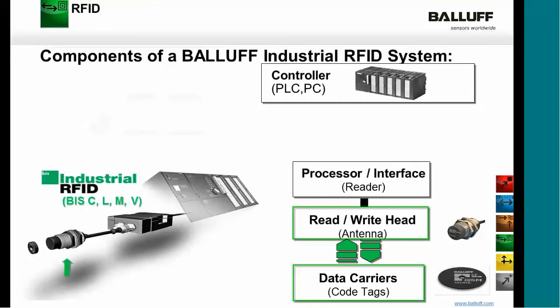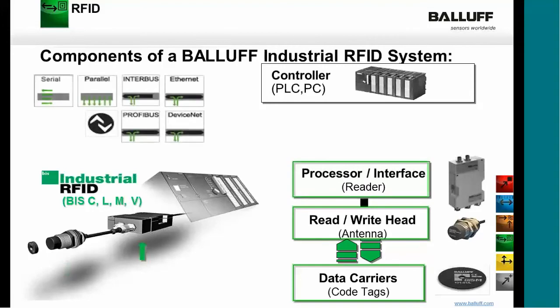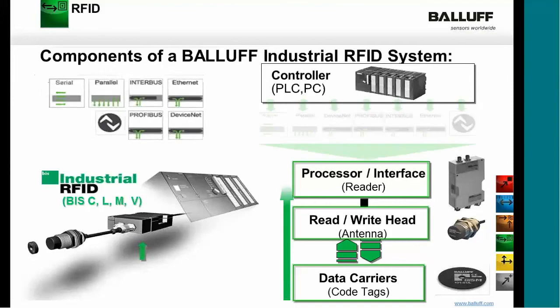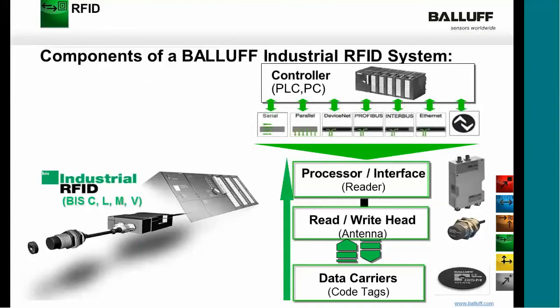And that connects to a processor. The processor serves as a main controller and a buffer for the memory. It sends commands back and forth from an outside source, and that would be either a controller, either a PLC or a PC type of controller. The processor will integrate into that controller using various bus systems. It could go serial or Ethernet TCP/IP if it was a PC application, or various industrial protocols like DeviceNet, Ethernet IP, Profibus, Profinet, EtherCAT if it's an industrial PLC.